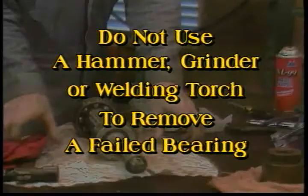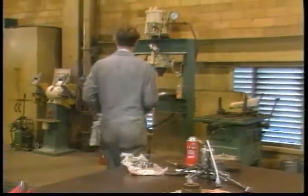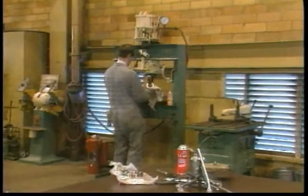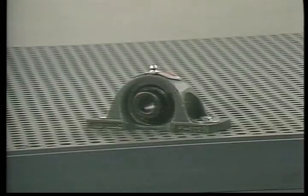Removing a failed bearing is often difficult. You may be tempted to break it off with a hammer, grind it off, or even use a welding torch to cut it off. These methods are dangerous and will usually damage the shaft or bore. The best practice when removing a failed bearing is to use a puller or a press adapter.